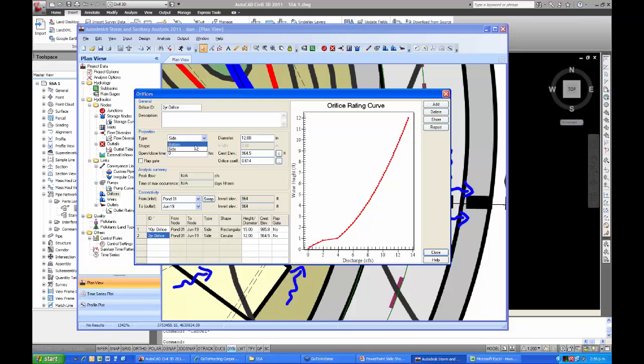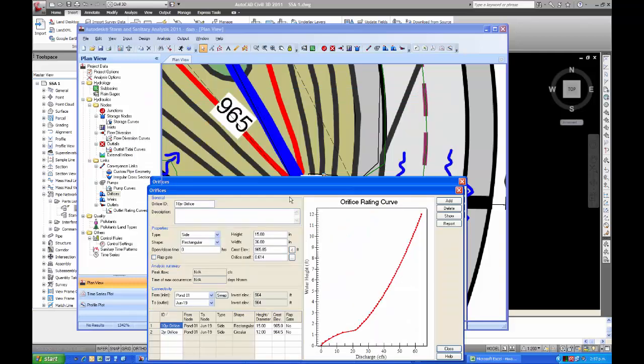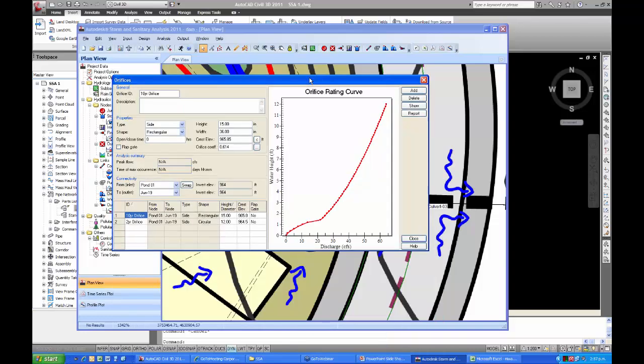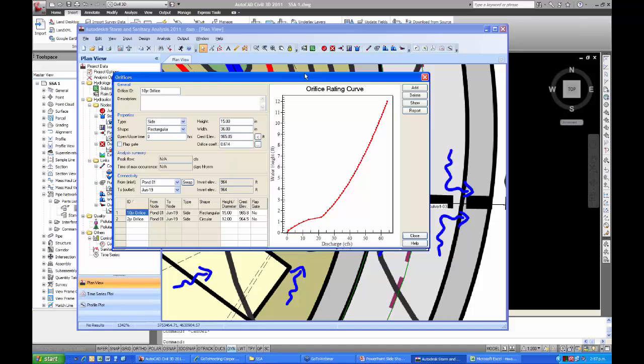Well, let's go and do it. So it's a bottom outlet, looks like that. If it was rectangular, it does change. Or a side, both side circular is what he's dealing with there, and that's the 2-year orifice, and obviously the 10-year orifice is here. It's a larger size, so it discharges at a different rate. Basically what they're doing there is matching the discharge of this developed area to the discharge that existed before this area was developed, so we don't overload the downstream creeks and other waterways, etc.